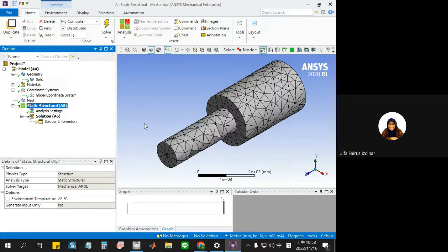And when we assign a boundary condition right here, like this one, we claim it's fixed on the wall. So for example, this is node number 12. In that case, because this is fixed, we are sure U12X, U12Y, U12Z are 0, because you say it's fixed.